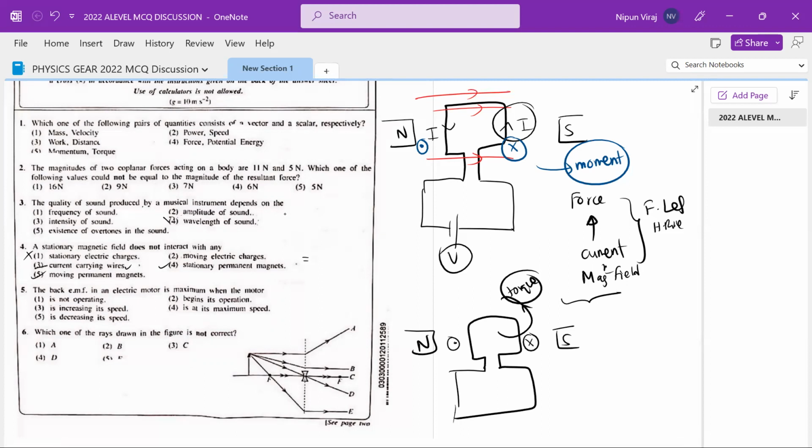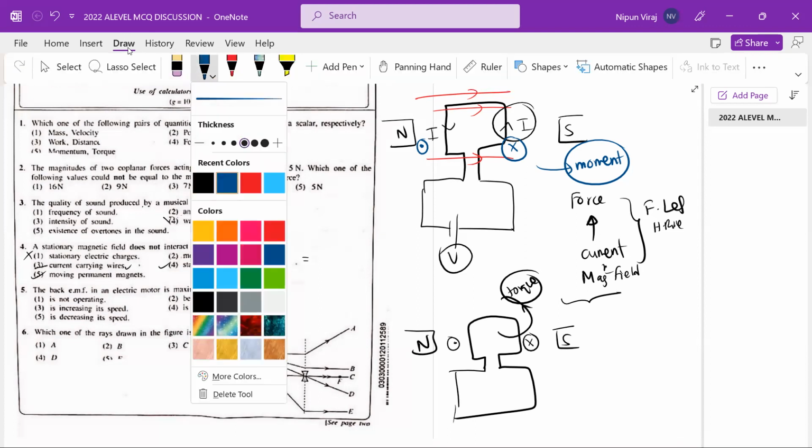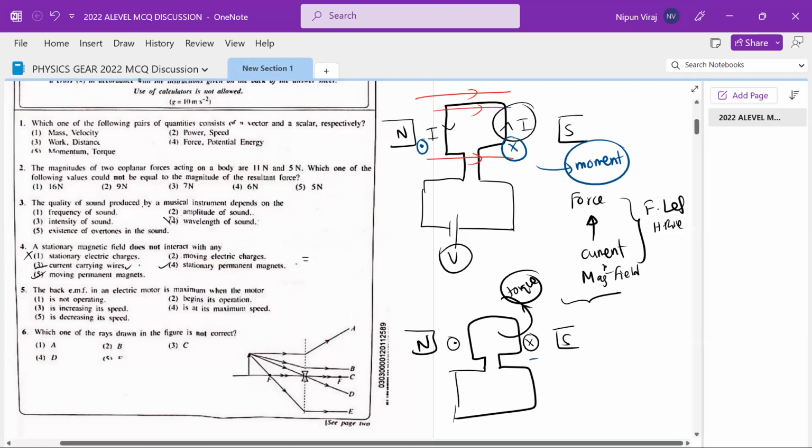According to the laws of electromagnetic induction, Faraday's law and Lenz's law, you know that if this happens, an EMF or a voltage will be produced. Definitely it should be produced. So let's take the right side first. There's a force acting downwards. In this situation, you have the force and the magnetic field, and current or EMF will be produced. Therefore, you use Fleming's right hand, not the left hand this time.